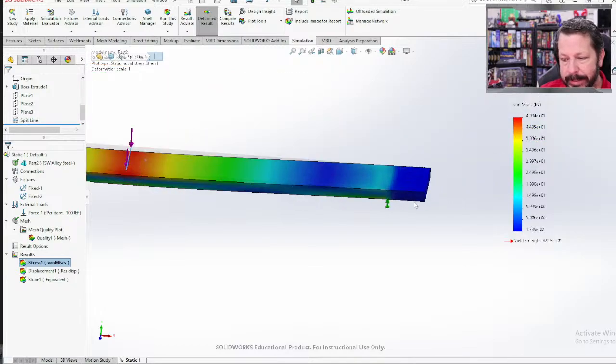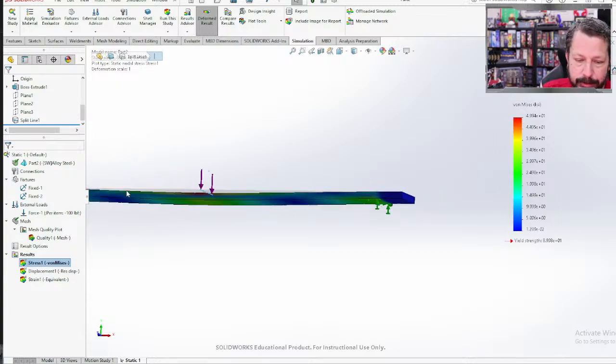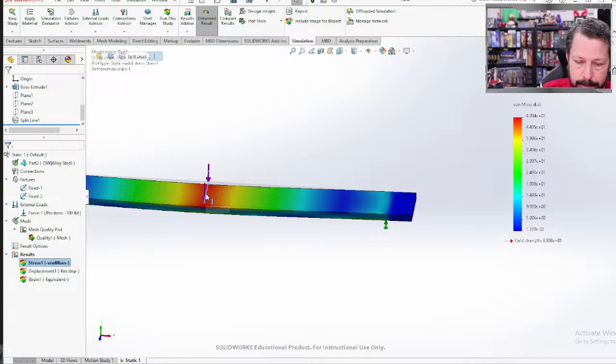But now that I've locked it down here, it's kind of adding tensile stresses everywhere, right? Because it wants to get shorter, but it's not allowed to, so it's stretching everything out. And I bet those tensile stresses are removing, or counteracting, some of that high compressive stress that's right under the load right here.